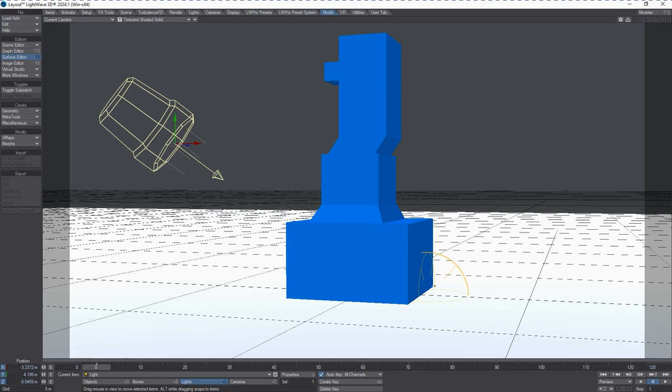Then in Lightwave, we introduced environment lights, which is what this is here. And this is kind of like a global illumination light, if you've ever heard that term. But it can do that global illumination without the work of a full-blown radiosity calculation. So it gives us the background infinitely in a sphere pointing towards our scene in the origin direction. Distant lights, very, very simple. Let's go back to VPR.